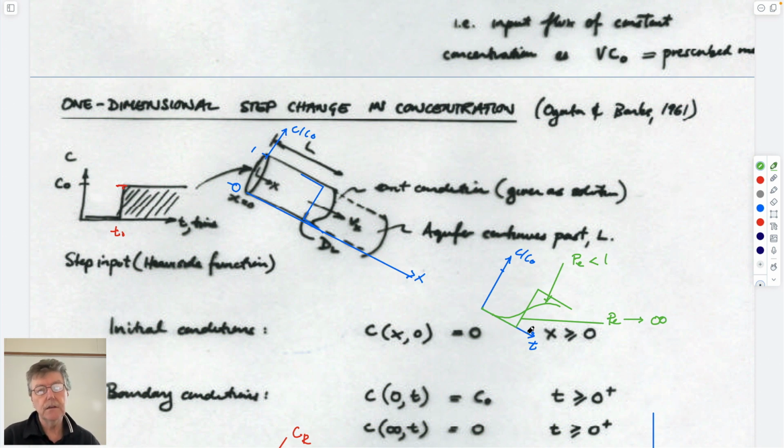And so if we can substitute values into that equation for the Peclet number and the Courant number, and if this is the core, this Courant number, TR equals 1, means that you filled a complete pore volume, so the plug flow is now arriving at this point when the Courant number is equal to 1.